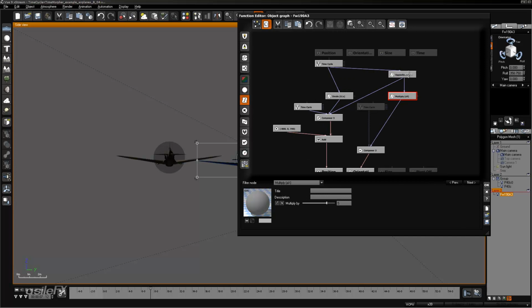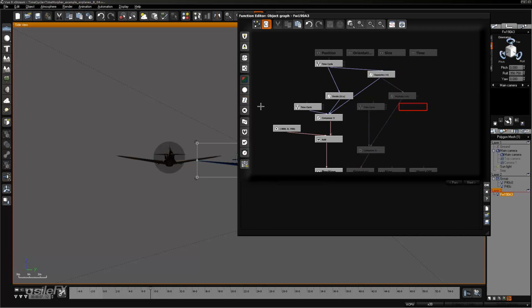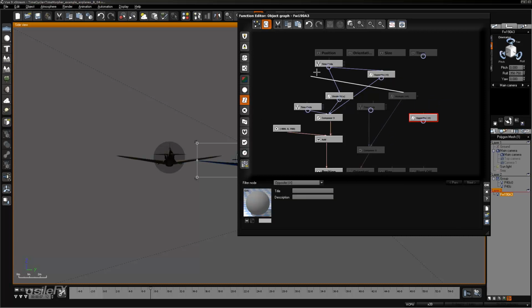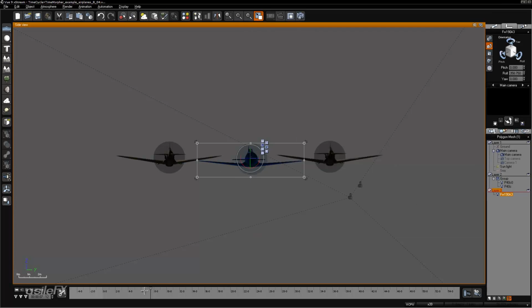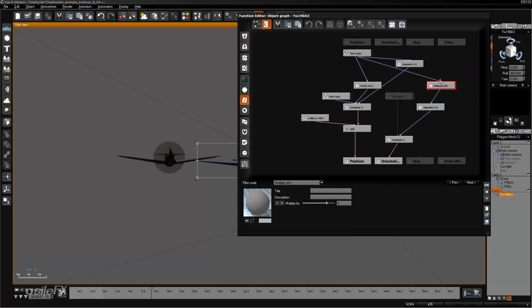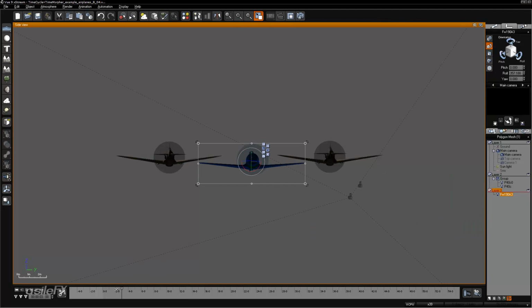So what we can do in that case is grab this opposite filter, selecting it, adding a new filter to create another opposite filter. And we're going to multiply the cycle distance first, and then do an opposite. And just try a higher value, 10.